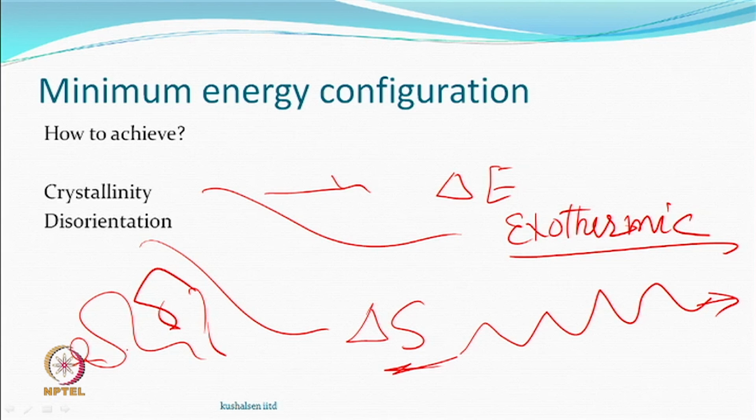and that is the reason why the textile materials, let us say synthetic fibers, as compared to any other material, when you heat them, they shrink. You have seen that? You believe it? If you have a metal, when you heat, it expands. But this is a very different material, where there are long chain molecules, and they have all to take a random position.